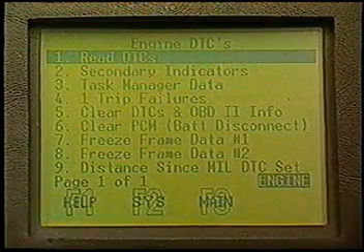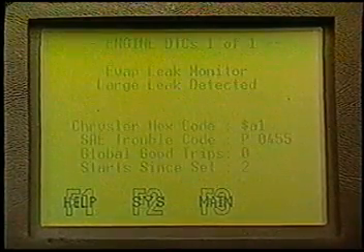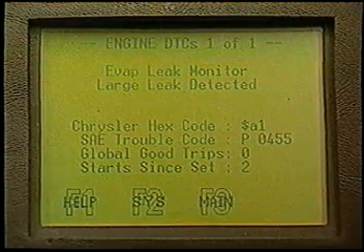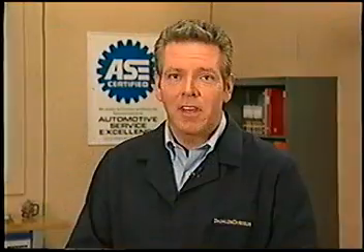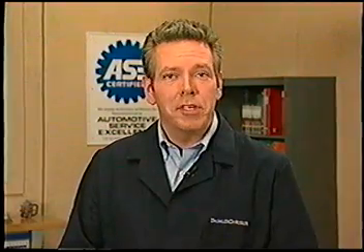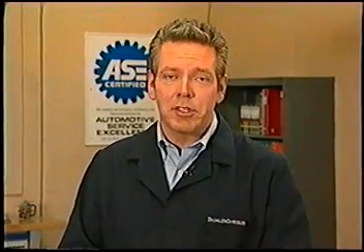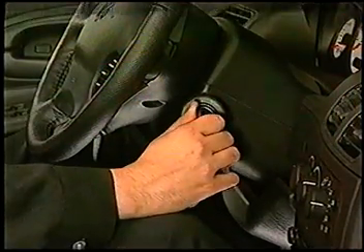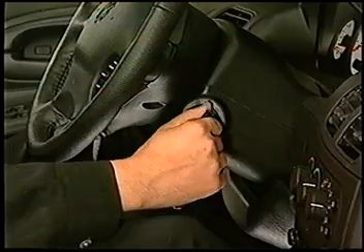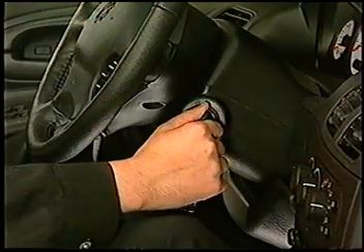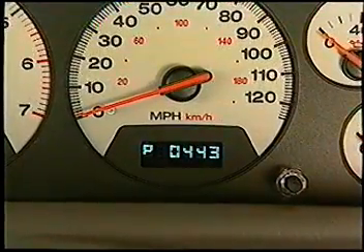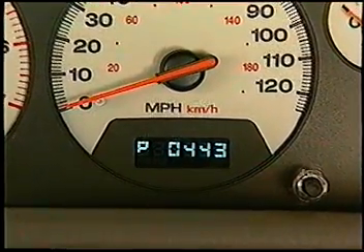When a vehicle comes to your dealership with the MIL illuminated, you can read the fault description by using the DRB3. And for 2001, PCM trouble codes can be displayed in the odometer on all vehicles, regardless of whether or not they use the PCI bus. By cycling the ignition key on, off, on, existing trouble codes will be displayed.